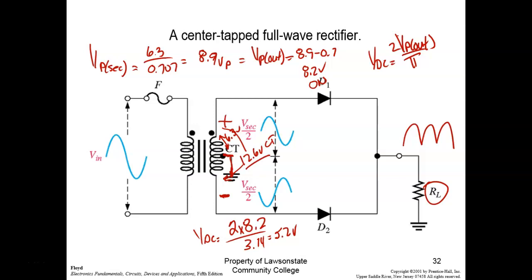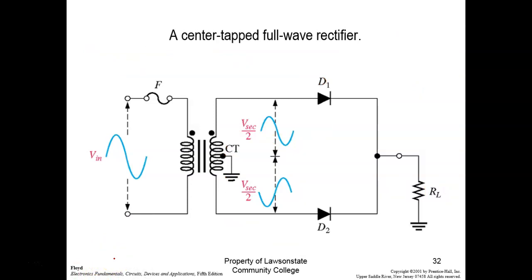I understand this. So what we're looking for are these formulas that say DC, and I think it says full wave CT. Is there any formula like that on there? It might not be CT. It might just be full wave. Yeah, so VP, V secondary, so this is my secondary voltage, divided by 2, which would give us what? 6.3. Y'all see the formula on there? Yes, no. What formula number is that? 13. 12.6. Yeah, it covers up. I'm sorry, guys.